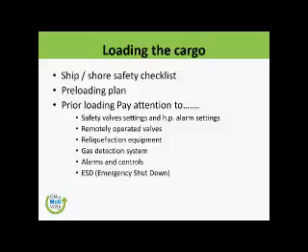We check the safety valve setting, HP alarm setting, remotely operated valve, reliquefaction equipment, gas detection systems, alarms and controls, and emergency shutdown. The emergency ESD test is one of the tests which we will do when we are alongside and prior to doing any operation.